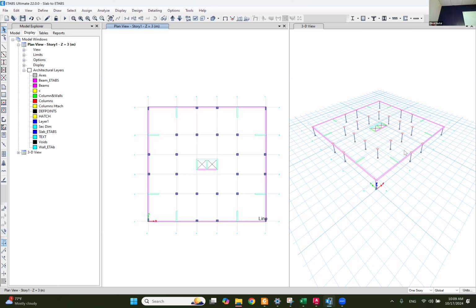By the way, you'll tell me there was a column that you made as a block, but I used another file that I created yesterday that was finished. But if a column is blocked with a hatch, the columns are not going to be assigned. So you'll find all of them have columns assigned except if the wall is in a block, not a polyline, it's not going to see it. For a broken line, it's not going to see it, okay? All right, so if you want to see the extruded view to make sure that the sizes of the columns are created properly.